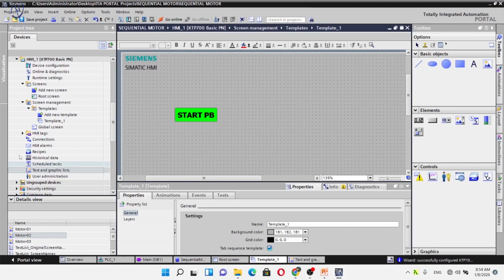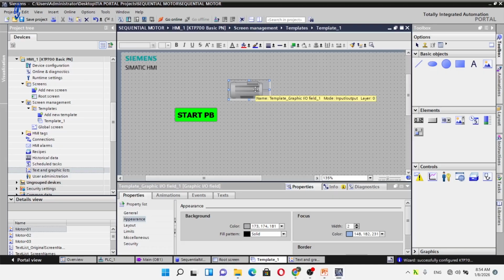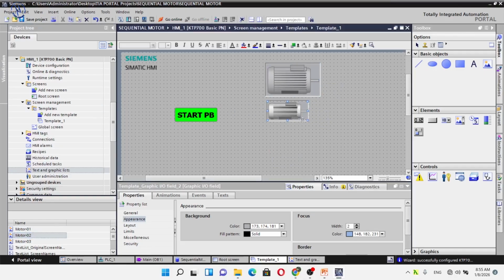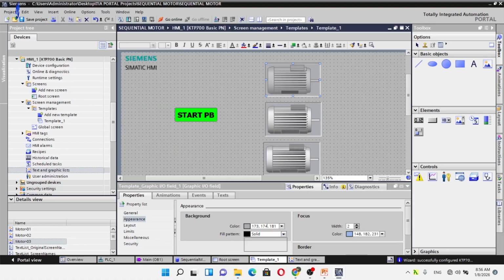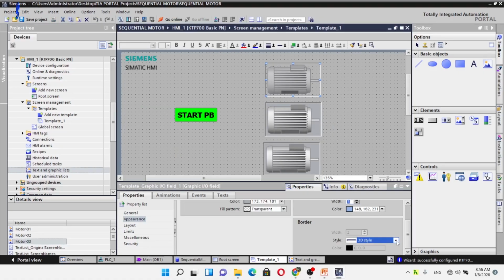Looping back, motor 3 runs for 10 seconds until timer T3 finishes. When T3Q closes in the first rung, it restarts motor 1. The cycle repeats. As motor 1 starts up again, its NC contact in the third rung opens, shutting down motor 3. The whole 30-second cycle, 10 seconds per motor, restarts from the beginning.